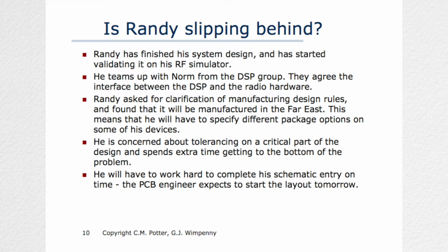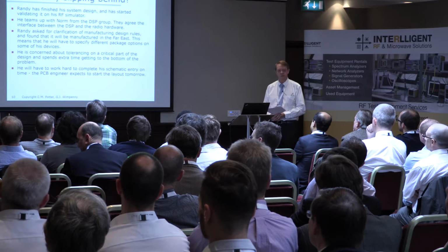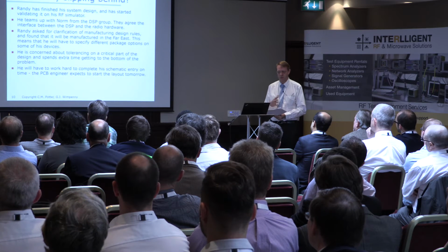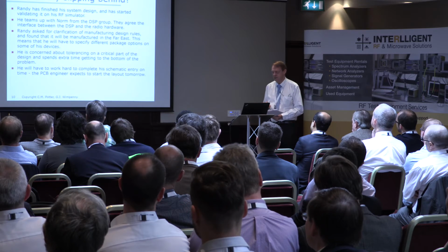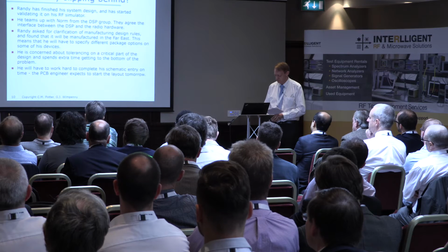He's also asked for some clarification of manufacturing rules. And this question has led to the realization that it's going to be manufactured in the Far East using a different set of components than are locally available. So he's able to figure out some of the different package styles, and particularly for RF, if you went from brand A of inductor to brand B of inductor, the parasitics are different, so he needs to actually factor that into his simulations as well.